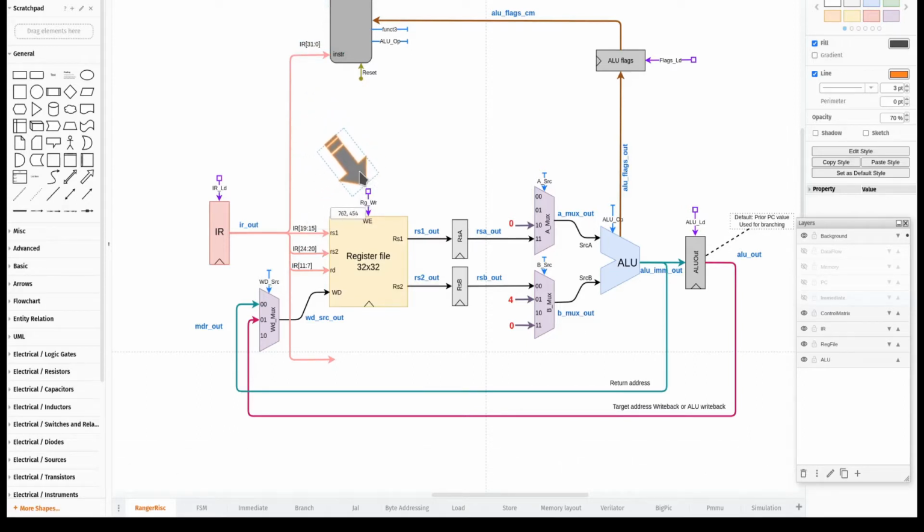Well, we need to first of all set the write. We'll eventually need to set this write signal. We need to control where the source is coming from with this signal right here. We also need to select both the RSA and the RSB via these two signals right here. And we need to select the operation that we're going to perform.